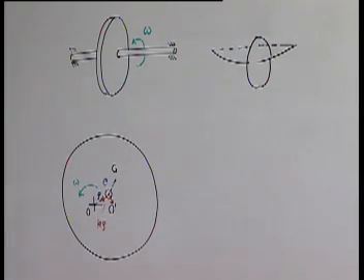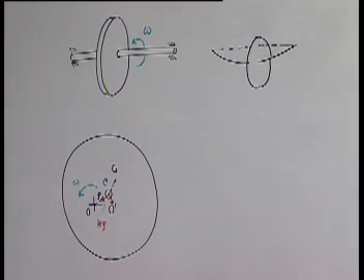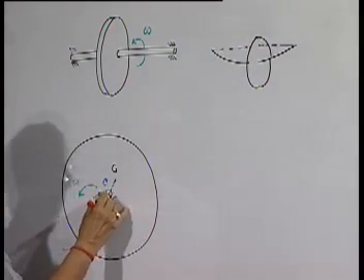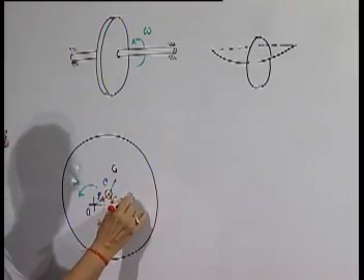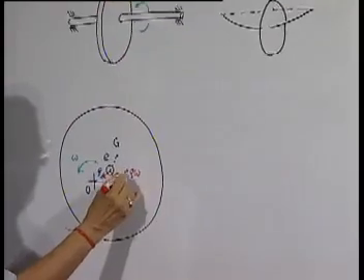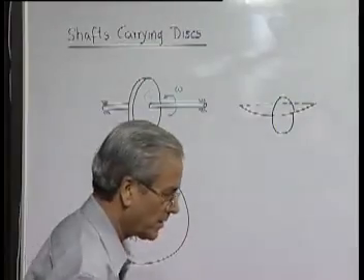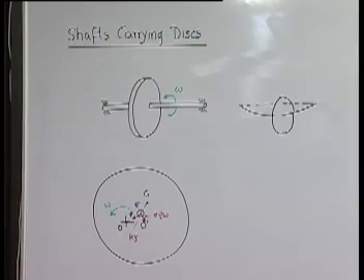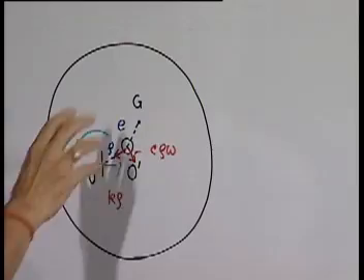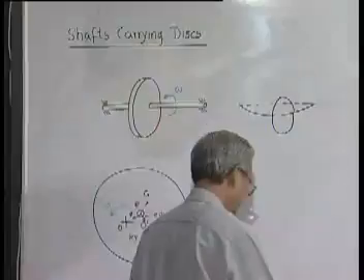That is the drag or friction by the fluid, and this magnitude will be equal to the velocity of this point, which is rho into omega, times the coefficient C, representing the viscous friction of the surrounding fluid. So, these are the two external forces acting, and let us look into the dynamics then.